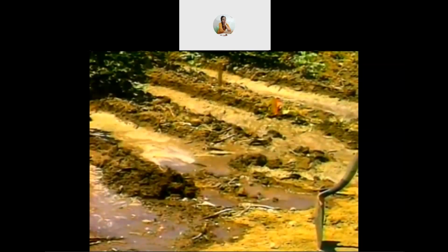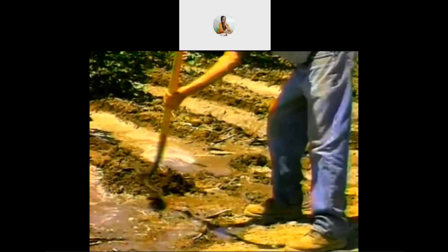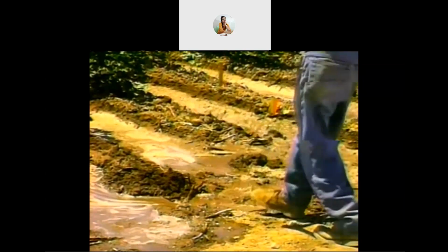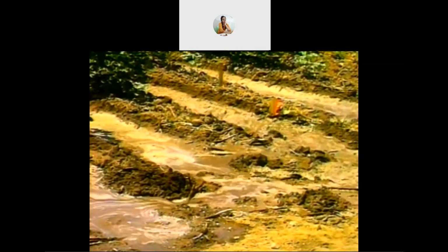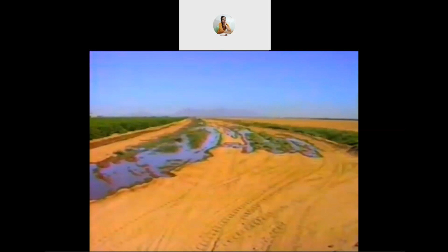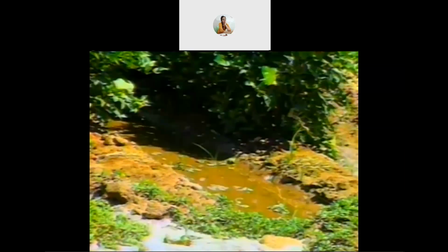Here are some more things to watch for while you're irrigating. If a row finishes early on a level or modified slope field, you can back water up into the row next to it. Make sure that water doesn't overtop the check. Don't let water flow onto roads, break out berms, or wash out the furrows. Don't let water pond for long periods, because this can damage some plants.